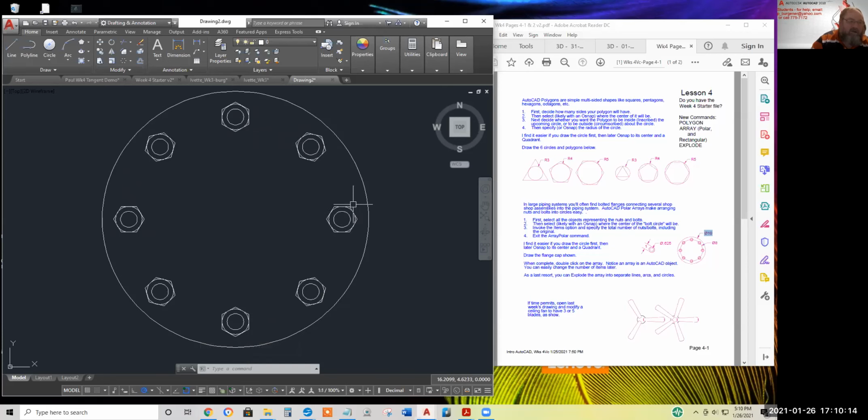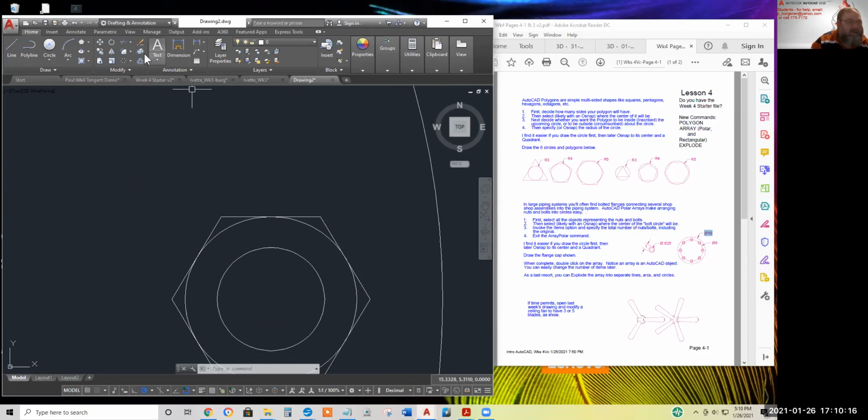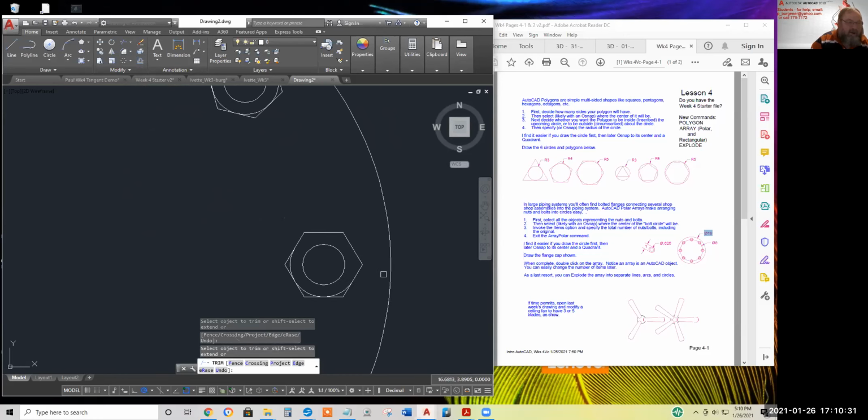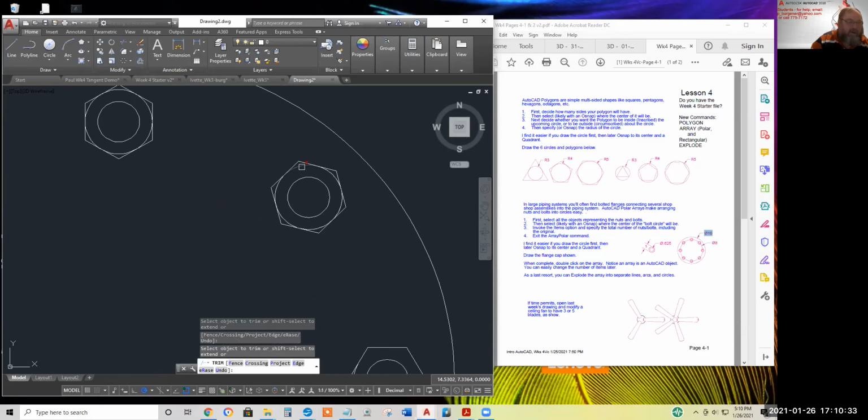Much more file intensive. We'll zoom in, launch the trim command, whittle away, whoops, forgot a step. Trim, enter, so everything's a cutting edge. Bear with me here, I'll just trim 3. Come up here and trim the same 3.